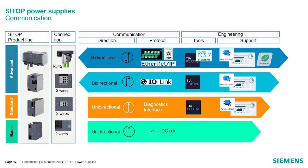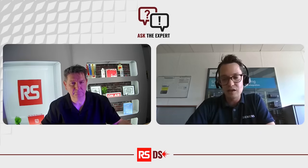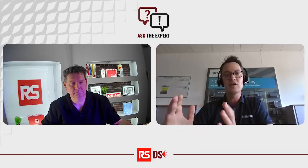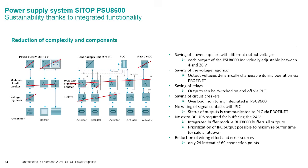And this is especially useful if you use different power supplies in one electrical cabinet, such as 5 volt, 10 volt, and 24 volt. You only need one power supply, and you can set different output voltages in different output channels. And therefore, you can also use the integrated selectivity function, and you can minimize the space in the cabinet, because I have a customer who needs different power supplies, many miniature circuit breakers, an external voltage regulator, and this you can all put together.